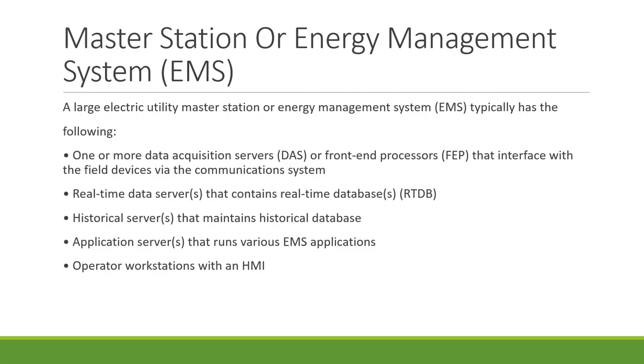That master station typically has the following things: one or more data acquisition servers, called DAS, or you can say front end processors, FEP, which interface with the field devices via the communication system. Real-time data servers will be there, which contain the real-time database, RTDB.